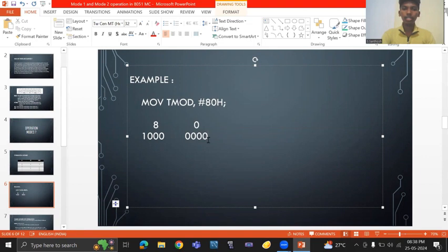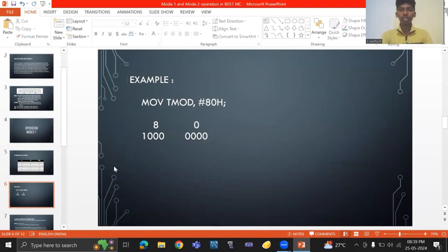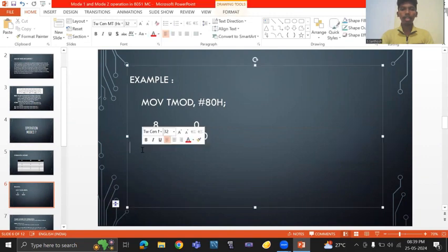And you saw that the timers take a 4-bit input on both timer 0 and timer 1. So depending on this input, we can say that the gate of timer 0 is actually not open, that is, it is on active low input, so it's not active. And timer 1 will stay active. You can see that timer 1 is active because the gate input is 1. And you can see that the M1 and M0 are 0, so it will be on mode 0.